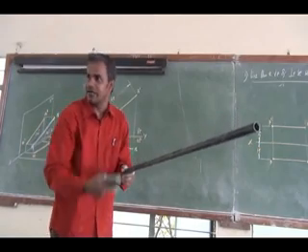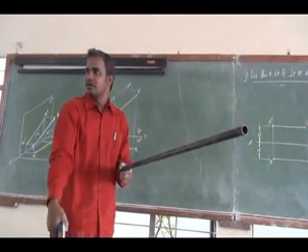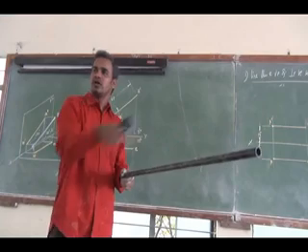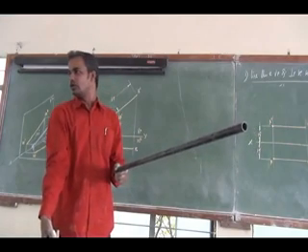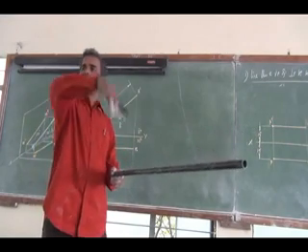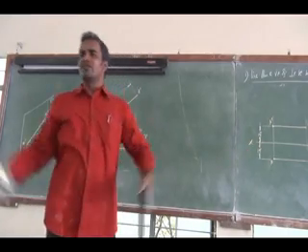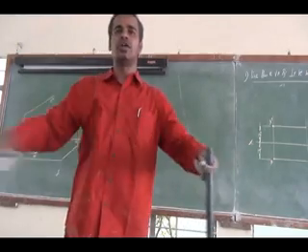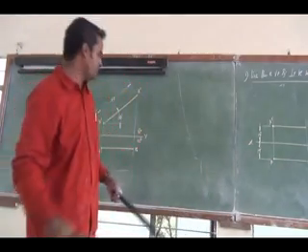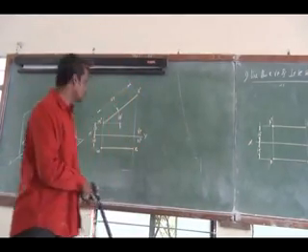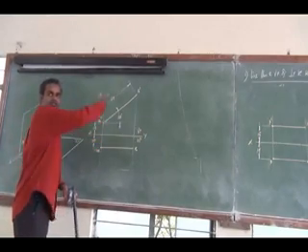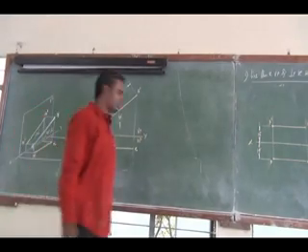Since it is parallel, I will obtain the true length there, and the same true inclination also on the top view. In the front view, a straight line with a shorter length will be obtained parallel to the reference line. Similarly, the reverse you will get.